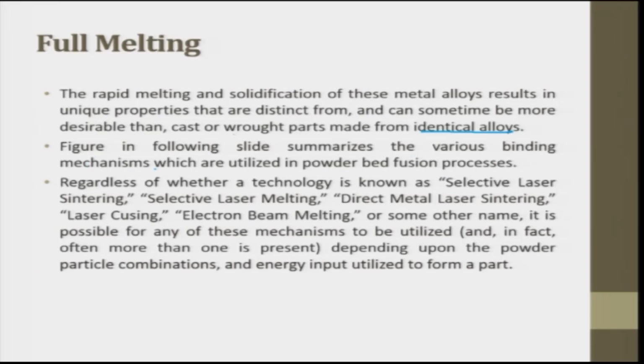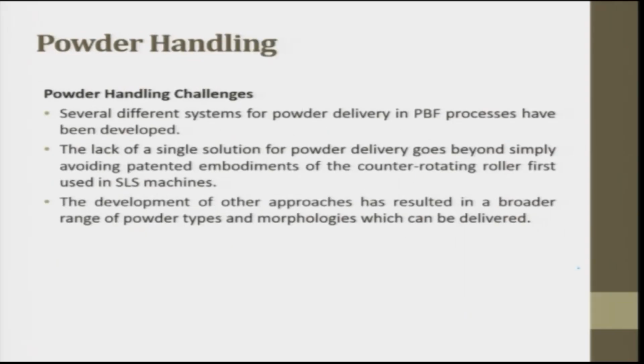The various binding mechanisms which are utilized in powder bed fusion process, regardless of whether a technology is known as selective laser sintering, selective laser melting, direct metal laser sintering, laser fusing, electron beam melting, or some other name, it is possible for any of these mechanisms to be utilized depending on the powder particle combination and energy input utilized to form a part. Powder handling challenges. These powders are not so easy to handle.